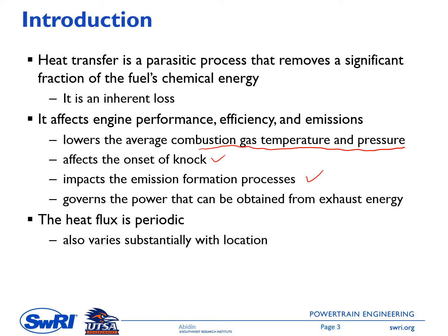This heat transfer also governs the power that can be obtained from exhaust energy. Minimizing the wall heat transfer in the chamber will increase the exhaust energy, which will increase the extraction of this exhaust energy by, for example, a turbocharger.